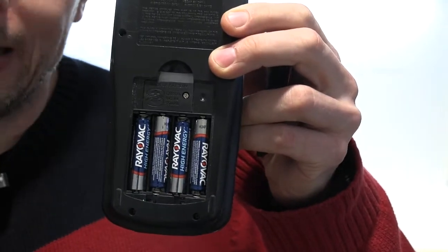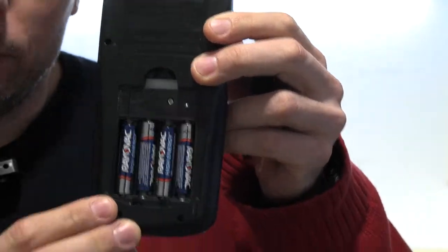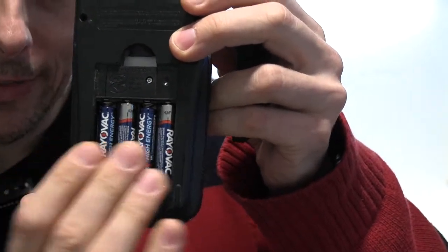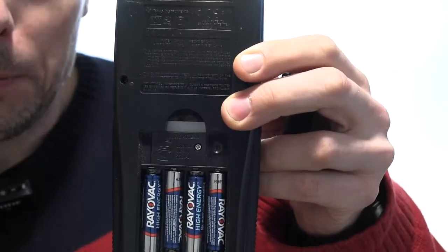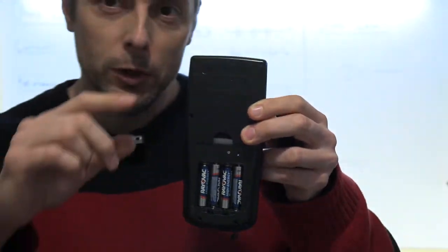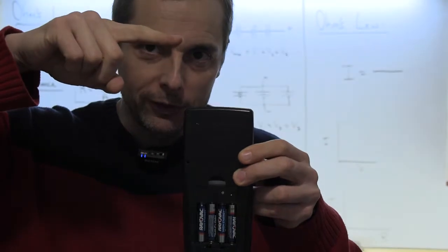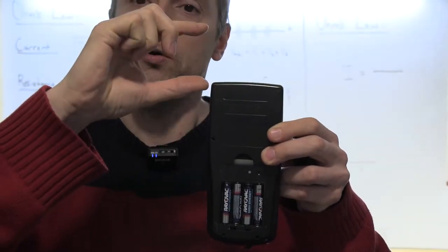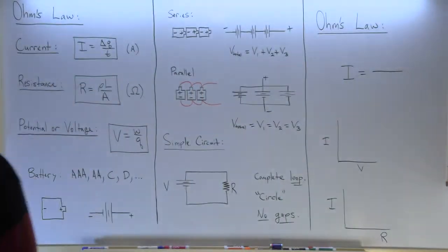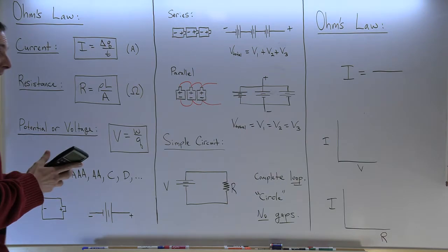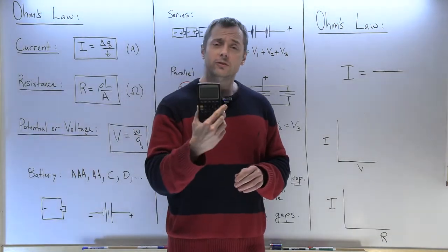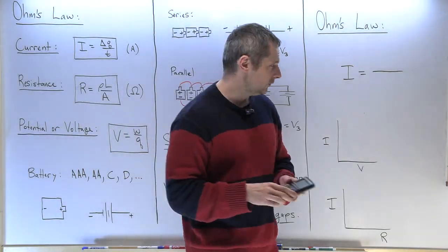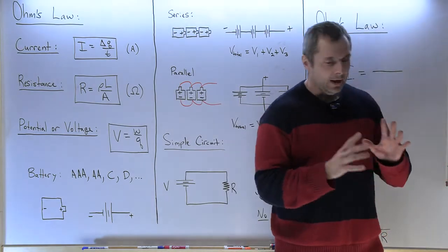6 volts. That's why. And the reason why they put them like this instead of end to end is a space-saving feature. You wouldn't want this calculator to have a little extra nub over here because the batteries have to be 4 in a row, right? You want them compact, so that's all. Okay, so that's batteries in series so that the calculator can run off of 6 volts, which is what it requires.